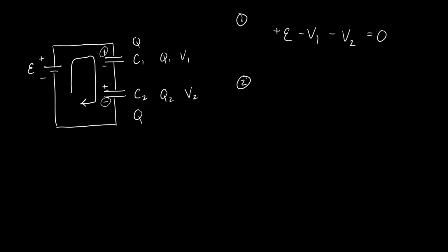So Kirchhoff's second rule creates a unique condition for capacitors in series. Capacitors in series will all level off to the same charge. I would strongly encourage you to write that down before you walk out. Capacitors in series all level off to the same charge. And we're not quite done here, but we got a lot of what I wanted to get done.